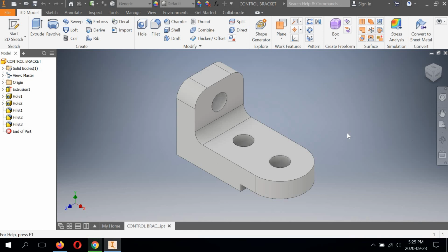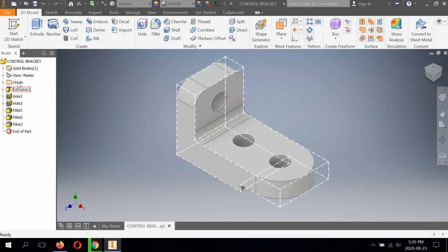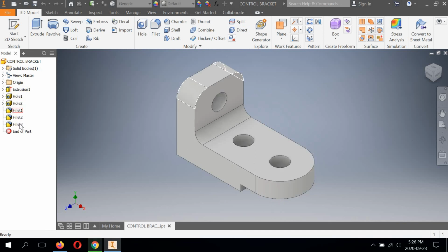We're going to be looking at some more drawing file creations like we did with the die punch in the very first drawing lesson. We're going to create drawing files for these two parts as well and add some dimensions next time. So until then, try this out. Good luck. Make sure if you're making mistakes as you go, don't delete and start over, but get into the habit of editing these things. Right? Features don't have embedded sketches. Only things like extrusions do. So something to note and to remember.